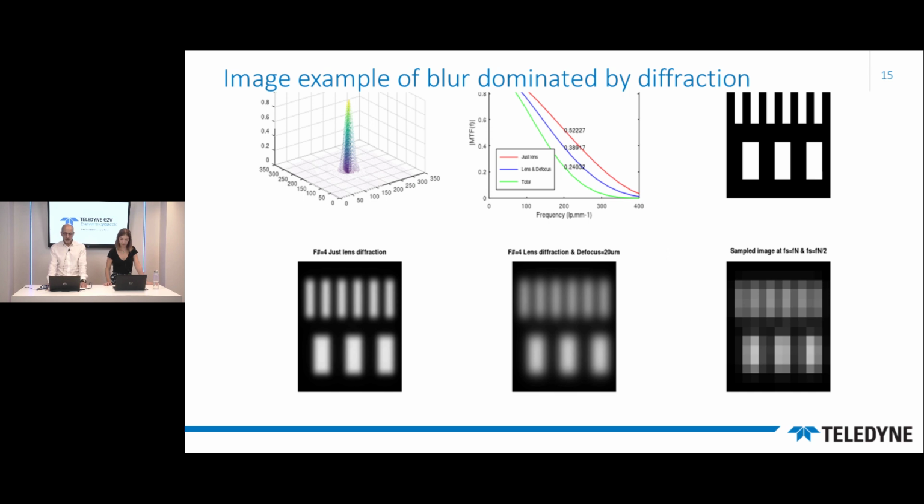These figures are the result of a simulation of the blurring effect on a Nyquist and half Nyquist contrast target. The target on the top right is the theory, whereas the target on the bottom right is the reality sampled by the pixel.